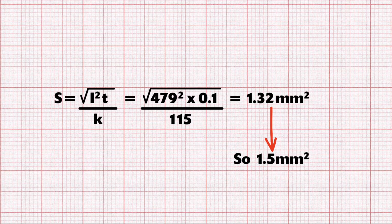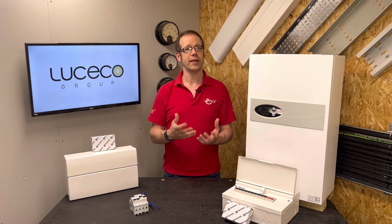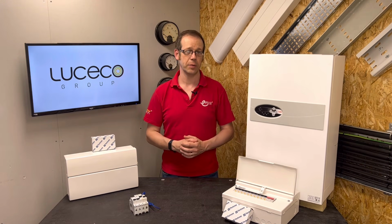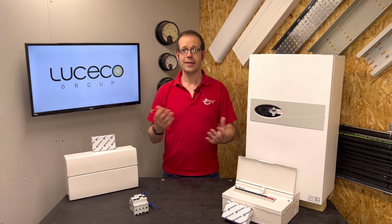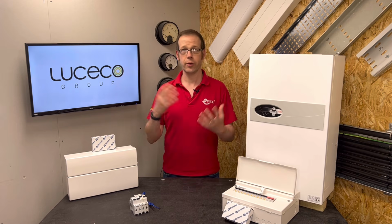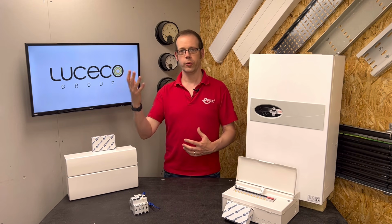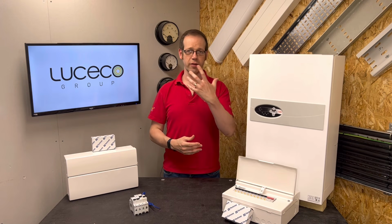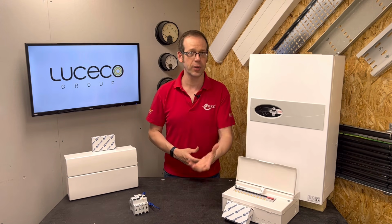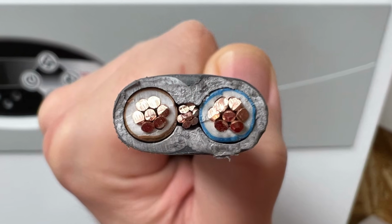It's a bit mad just how small we can make our CPC, isn't it? And if you remember, we said that the CPC in our 10mm cable had a CSA of 4 millimetres squared. So because that's plenty big enough and getting a specialised cable with a 1.5mm CPC would be wildly cost prohibitive, and if we did change it now, that would affect our earth fault loop impedance value, which would also change our fault current size, which might change our tripping time, and therefore our adiabatic equation would have a different outcome, we might as well stick with the standard cable, eh?